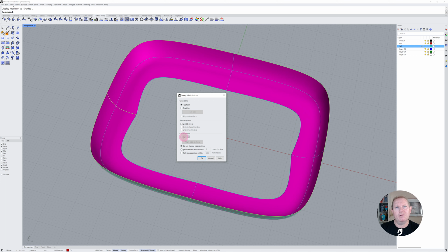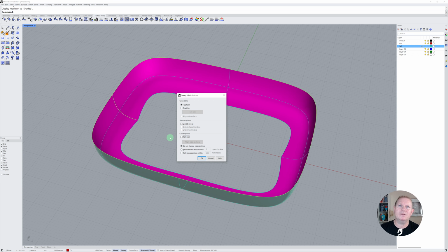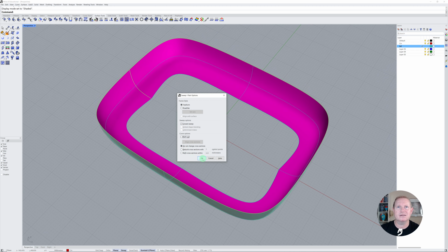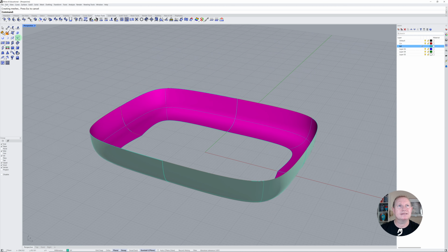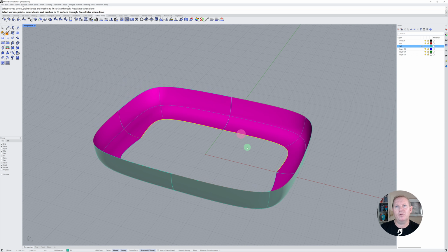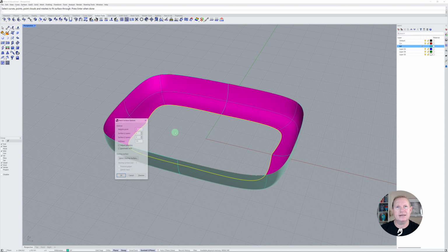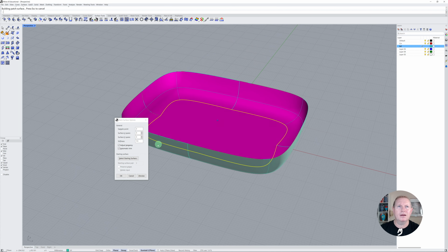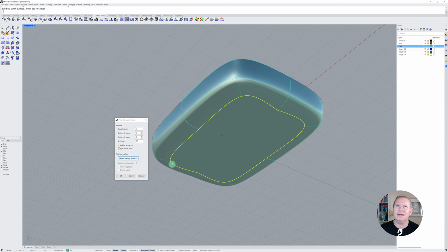Let's turn refit rail off and you'll note what happens here. We get this bump. Let's have a look what happens if we patch this and we don't refit rail around this surface. Alright, so there's our surface. Let's get our patch. Let's choose these four edges now. Press enter. Do a preview. And we can see our patched surface there where we didn't rebuild.